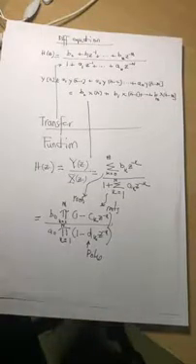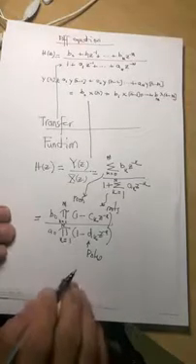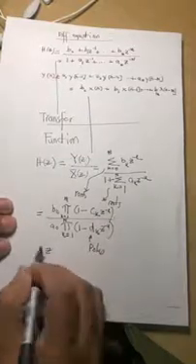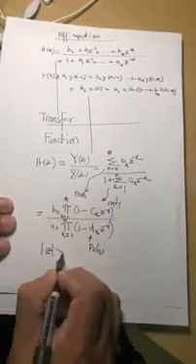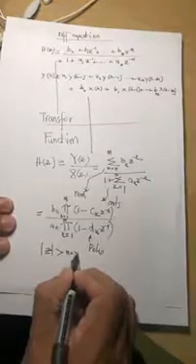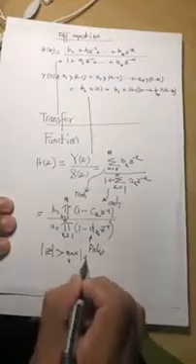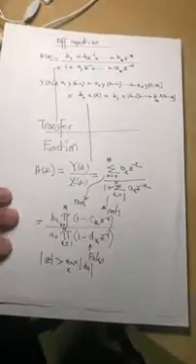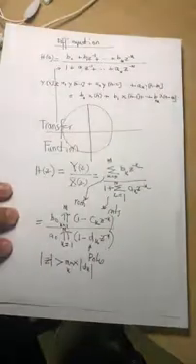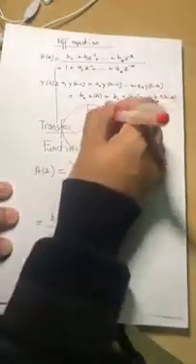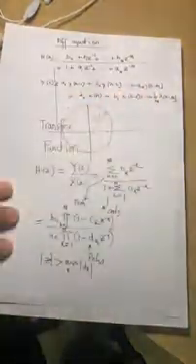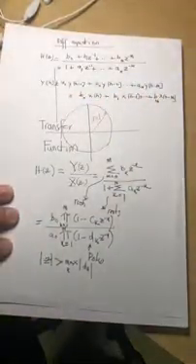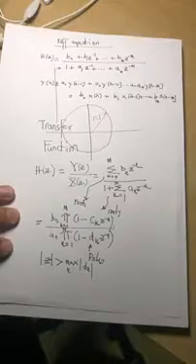And we need to find out the pole that has the maximum magnitude. Outside the outermost pole, the pole that has the maximum magnitude, is the region of convergence. So remember drawing the circle with red color. This is a unit circle, because R is equal to 1. This is a very important circle, and now you plot all the poles.